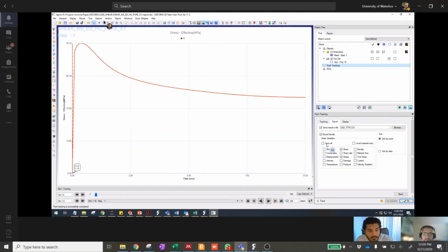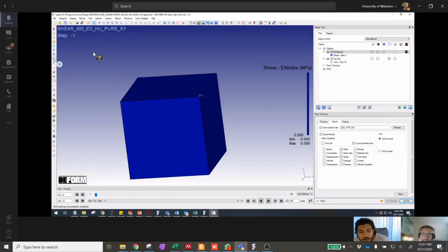Right now I can't have the effective stress being graphed. Okay, how do you configure what happens? Can you change the axes or whatever here? How do you configure this plot, say this curve here? How did you do that? That's done through here, and then instead of showing effective, can you show something else? If I do displacement and then I do track.